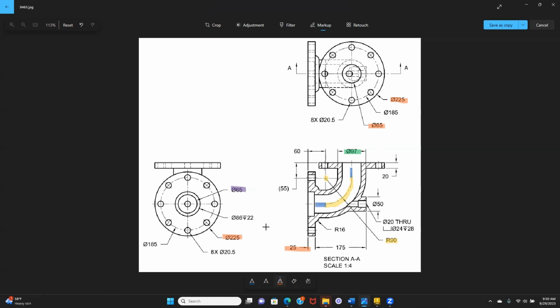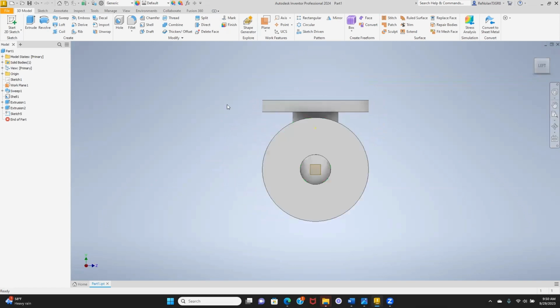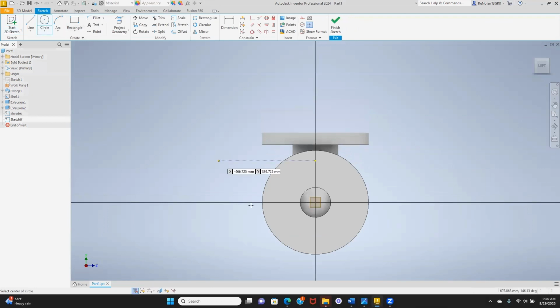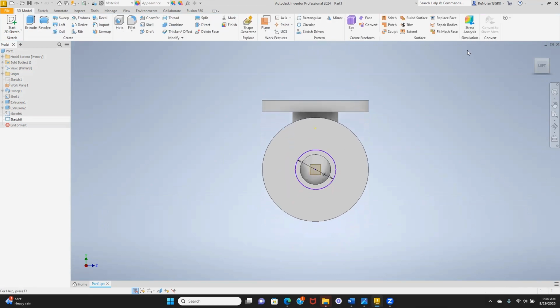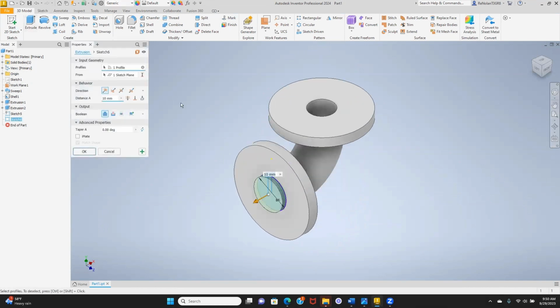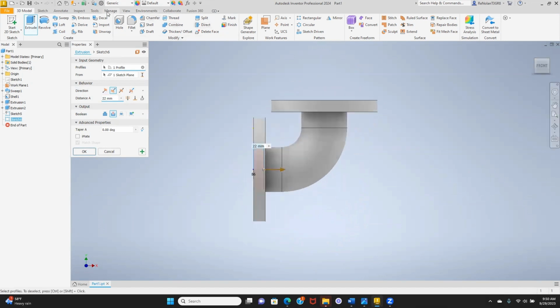We see that there is this little, I'm going to call it a countersink type area. And that area is not as deep as the face itself. Remember, when we are doing sketches, we only want to sketch consistent extrusion distances. So for example, with this plate, that center hole is a different extrusion distance than the patterned holes that go around the circle that are used to connect the fitting to something else.